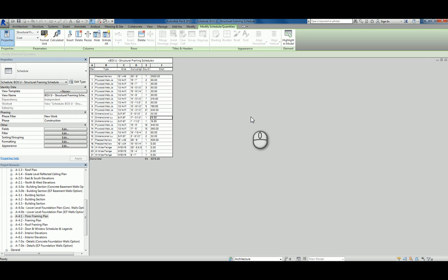Anyways, that's the kind of thing that gets confusing with these particular things, because you might be using SA in your model, and it might be extended to deck. So if you give me square footage of SA, it's going to be a completely bad number, right? SA should only go to 8 foot. You might have it going up 12 foot. So now it throws my costs off. Yeah, and that goes back to garbage in, garbage out, how it's modeled, right? If you're saying the intent is that this wall stops 6 inches above the ceiling, but you actually have it modeled up to deck, and you don't know it's modeled up to deck, that number that you're producing isn't accurate.